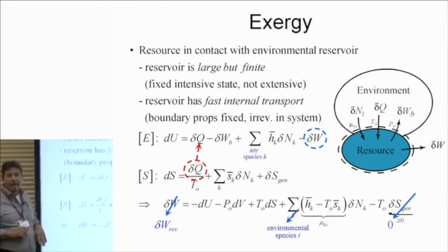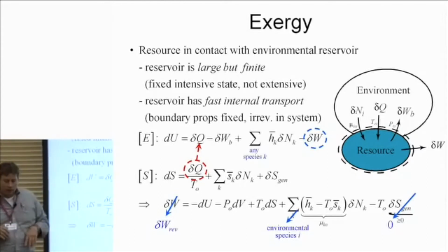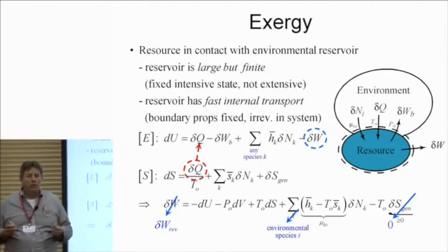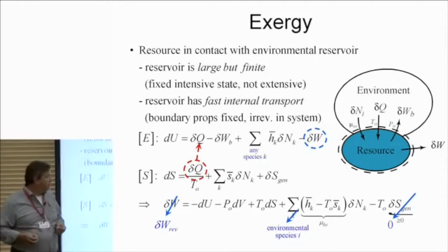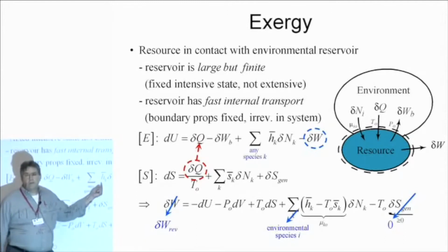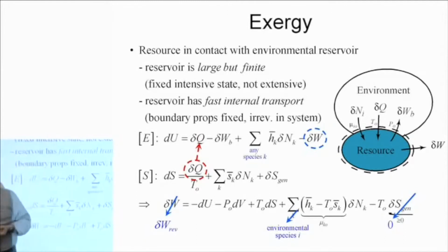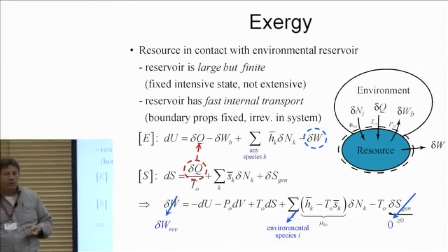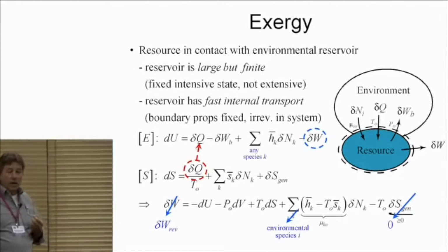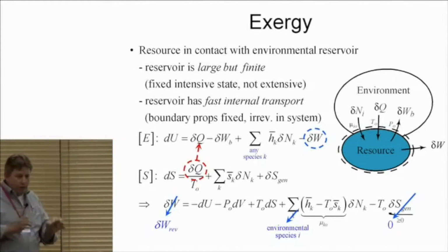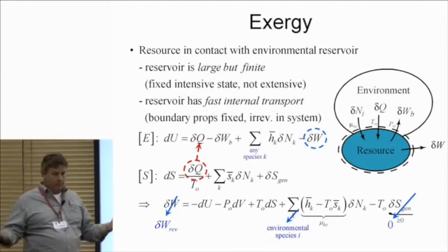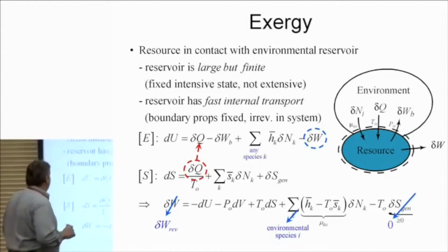Well, I actually meant something slightly deeper as well. You've got a hidden meaning there, the bar on the top. That's per mole. So it's also partial molar enthalpy there? Yes, because I'm transferring per mole. So N is a molar transfer. If I take the bar off, it's per mass, so that'd be a delta M. No, what I meant is the partial molar enthalpy, it's a multi-component system. Absolutely. So it is the enthalpy carried by that particular species in its mixture. It's completely general.